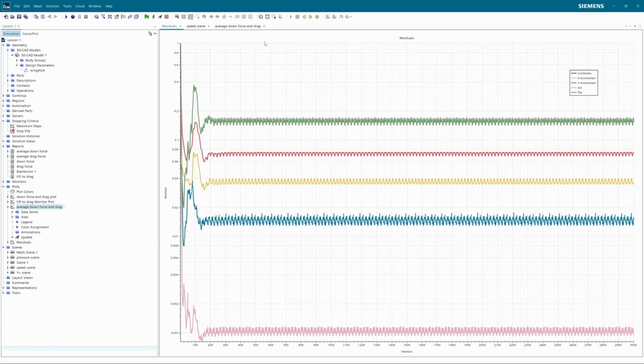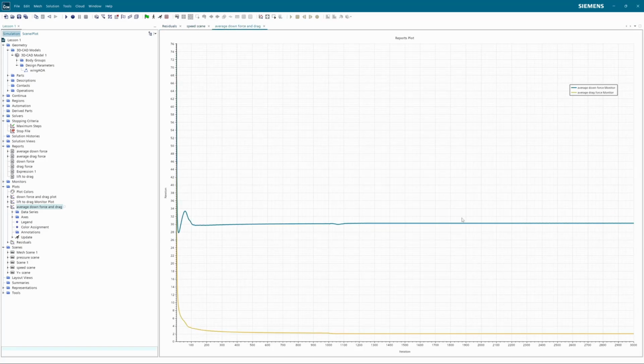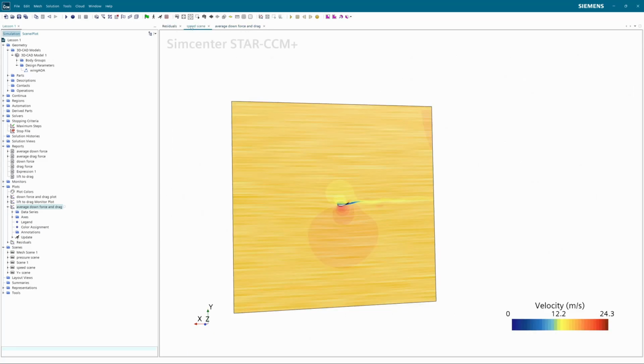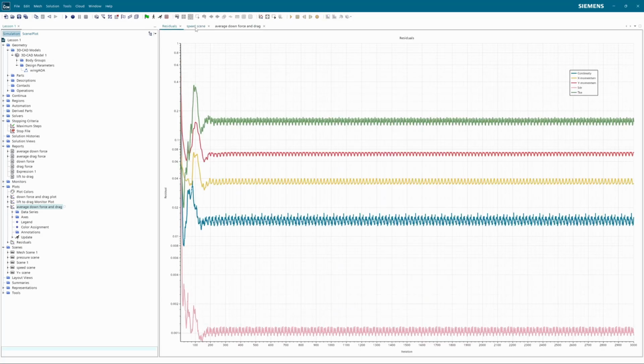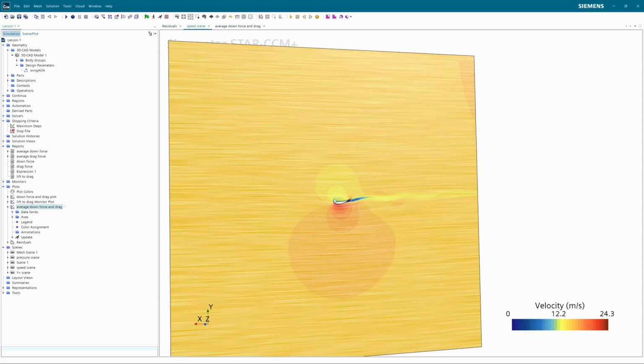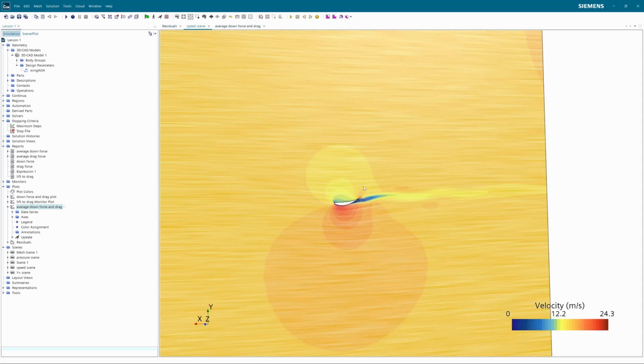While some 3D simulations can take hours to run just to get one result like this, just to do maybe 1,000, 2,000 iterations. So the speed is definitely the advantage of this, certainly when you're optimizing things and changing things, and testing just the characteristics of your wing profiles. It's very useful for that. But do know that 2D simulations are actually quite simplified compared to regular 3D simulations.